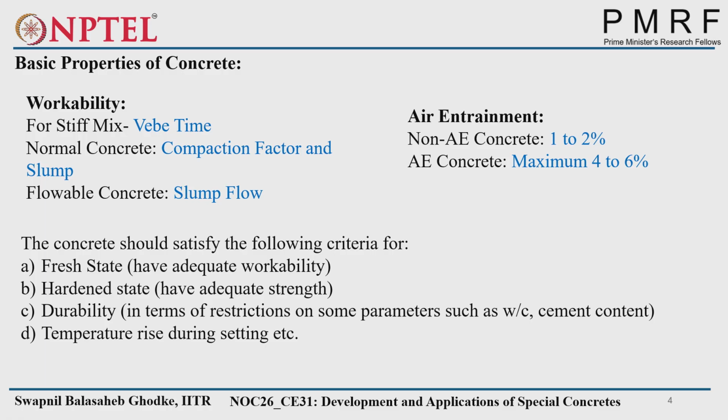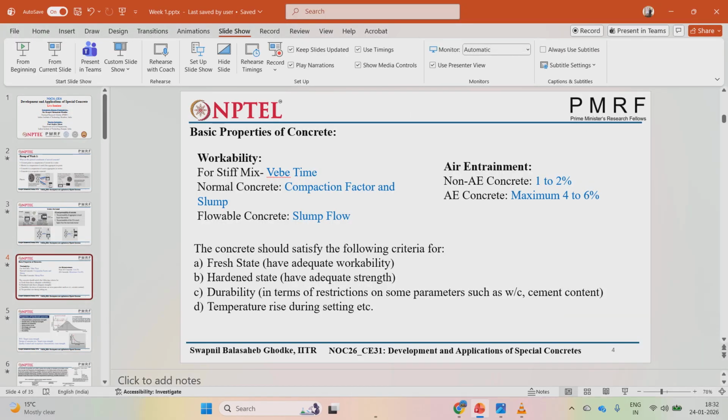While casting that, what happens? There is a temperature difference between the surface and the core. If that difference is large, thermal cracks can happen. So that's why.